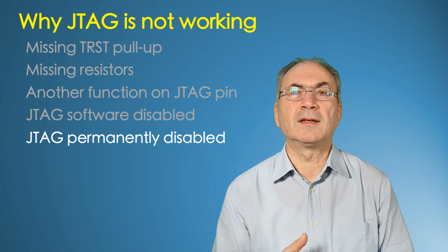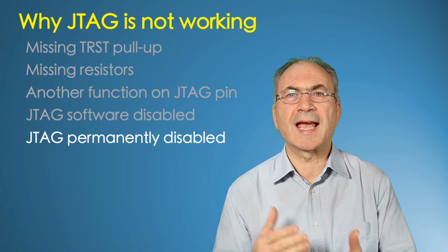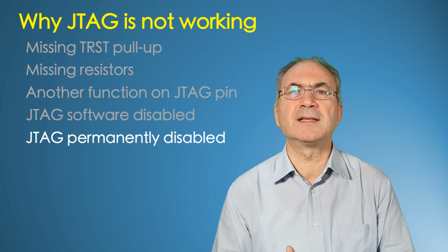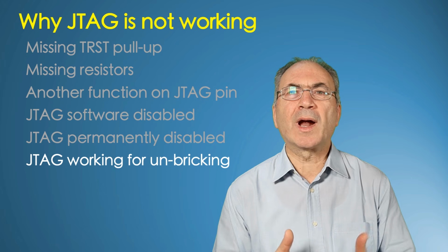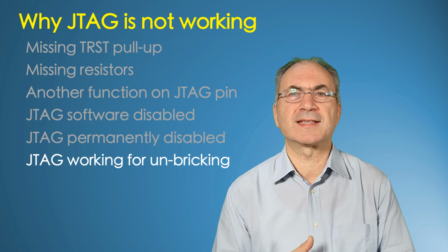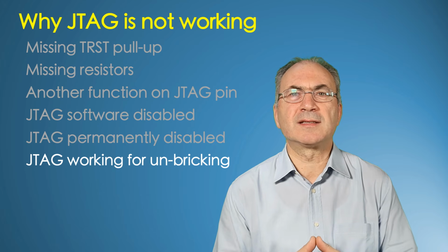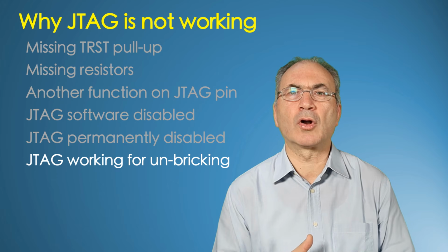If the JTAG interface has not been permanently disabled, usually it will be available when our IoT device cannot boot. Maybe it is a corrupted bootloader.